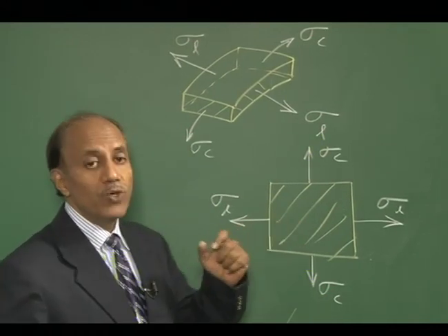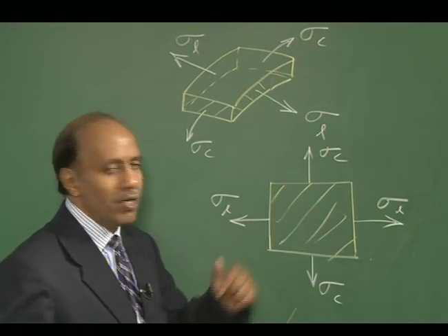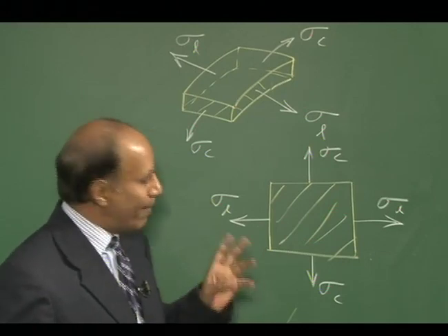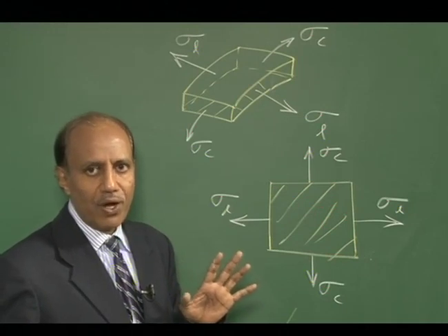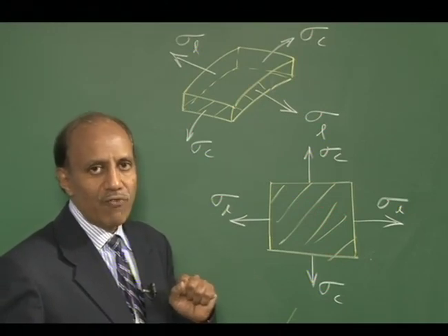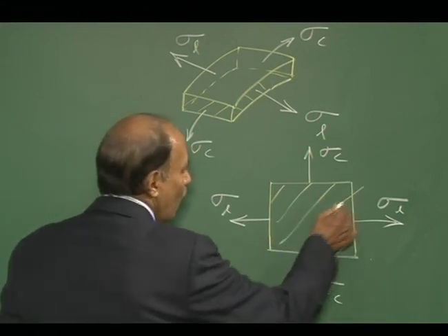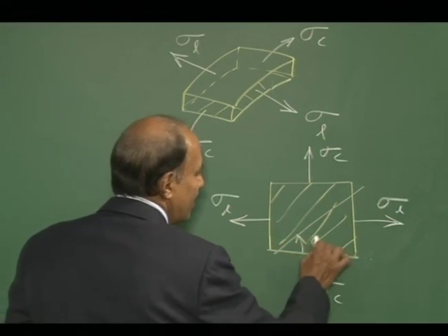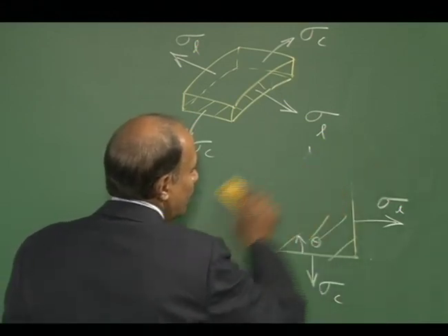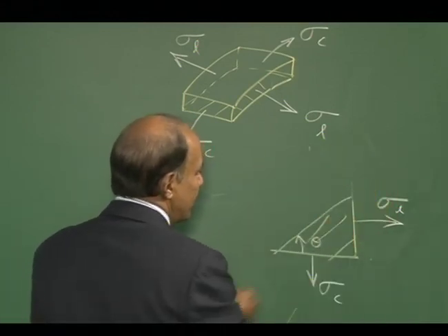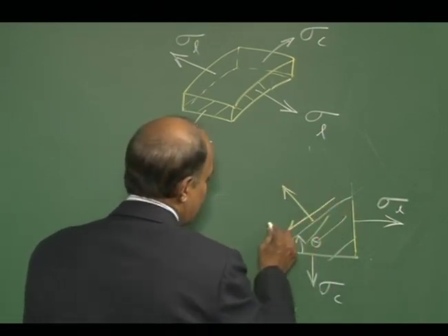So, an element subjected to more than one stress, here in this case two normal stresses. Right now, on the boundary you do not have any shear stress. But understand, if you take some plane within the element, any plane inclined at an angle theta, this plane will be subjected to some normal stress and some shearing stress, sigma s.